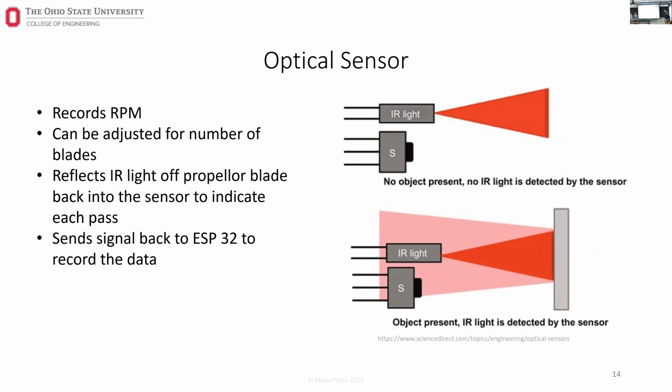That won't necessarily work for our new design because they want to use 3 different interchangeable motors of all different sizes, so that we calibrate differently. So we're going to do it by pointing at the propeller. We've programmed it so that it will count every time the propeller passes by, and the ESP32 is programmed to divide by the number of propellers that's inputted by the user.